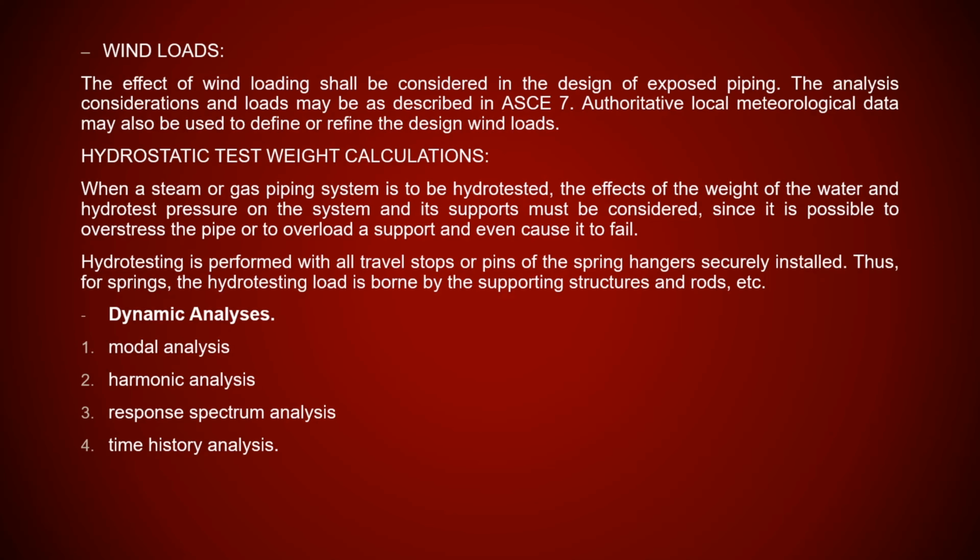Harmonic analysis is mainly used to predict the vibration, and you cannot perform the harmonic analysis without having a modal analysis. Response spectrum is mainly used for seismic studies, and time history analysis is usually used for pressure relief valves or anything that has a time history to be studied.